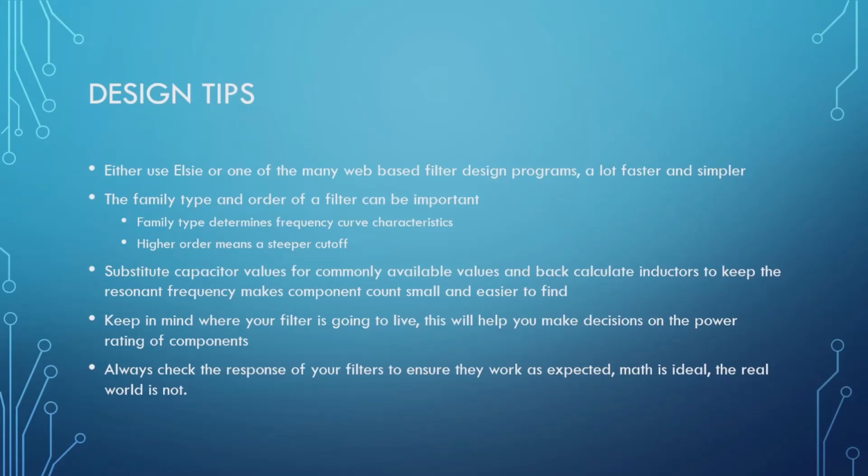They come in like 1, 2.2, 4.7 microhenries, or 470, 680 nanohenries and things like that. So you want to choose an obtainable value of a part, then calculate your capacitor value using that particular inductor, and then choose the closest capacitor you can get.